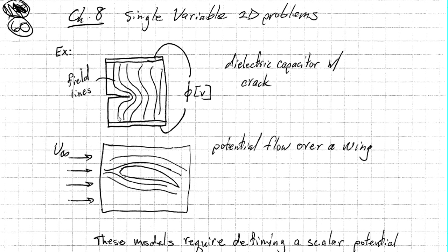So I'll talk about the PDEs that govern this and how we can solve those PDEs using the finite element method. It turns out the same PDE will solve potential flow over some solid boundary. Now there are certain approximations to the flow. Hence, if you're familiar with potential flow, the fact that it's irrotational means that you've made certain approximations. But in those limits, you can solve this with a simple scalar potential.